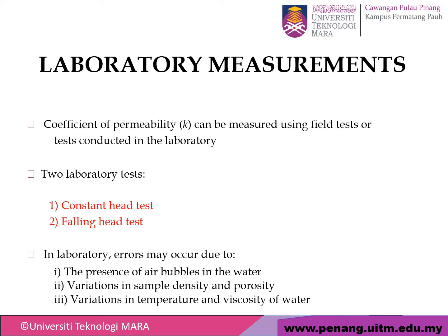Alright, now we go to the laboratory measurement. Coefficient of permeability K can be measured using field tests or tests conducted in the laboratory. So we have two laboratory tests. First is the constant head test and second is the falling head test. The difference is that the constant head test is for coarse soil, and the falling head test is for fine soil.